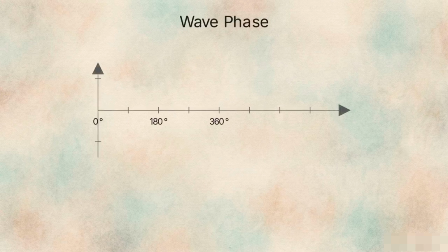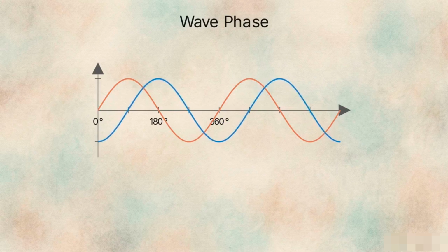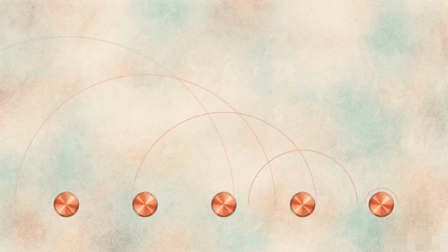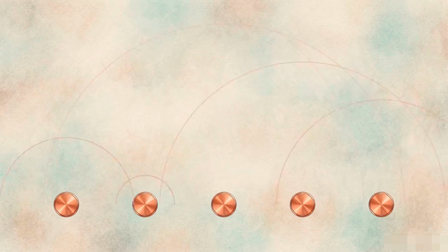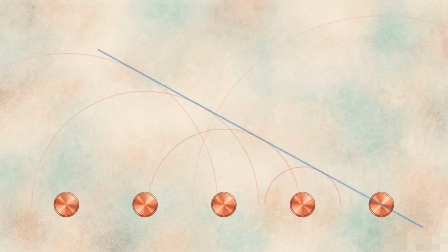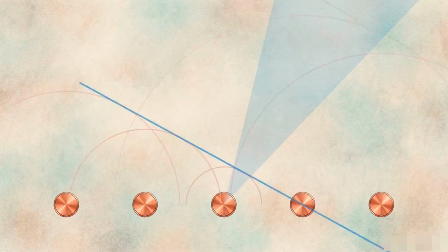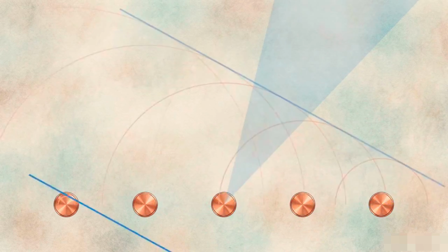This profile demonstrates wave phase, the specific degree alignment of a wave cycle from 0 to 359 degrees. By shifting the timing of the cycle, we create a phase delay. To steer the beam, the system applies highly specific, sequential phase delays to the signal across the adjacent columns of antennas. Because antennas on one side emit their peaks slightly later than the ones opposite to them, the resulting plane of constructive interference forms at an angle. Sequentially delaying the emission physically tilts the beam.